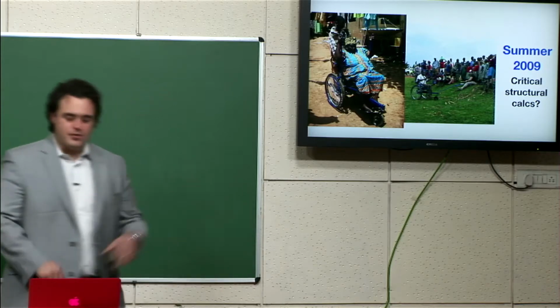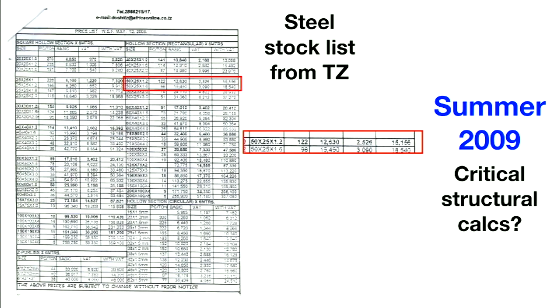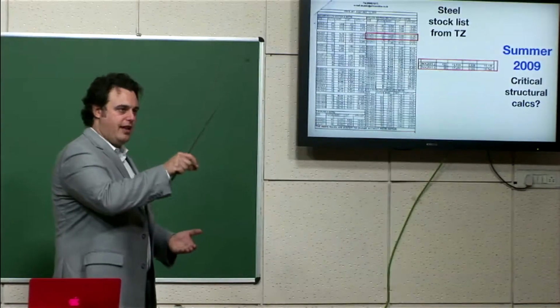So we had to think about those things. Okay. So, as part of that too, you already pointed out the rectangular cross-section. I had to go to steel suppliers in East Africa to understand what steel we could actually get, so we could choose a relatively high strength to weight ratio box section of tubing.